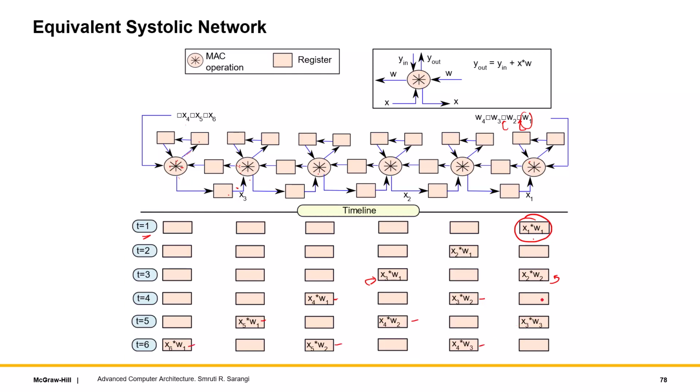So what's happening is that it is taking more time. I'm doing exactly the same set of computations, but my throughput has reduced to half. So 50% of the time I'm not doing anything. If we take a look at this combinational unit, I'm doing one multiplication, then nothing, then I multiply and add, which is what this is supposed to do. And then I'm doing nothing, then I multiply and add, and then I'm doing nothing. The same is true for the rest of the units. I'm computing exactly what I was computing earlier, but in this case there is an idle time of 50%, right?